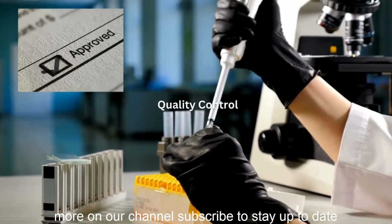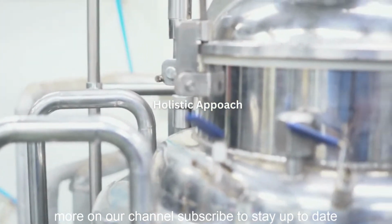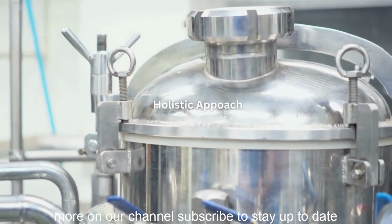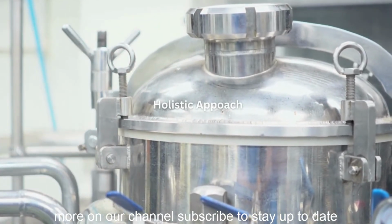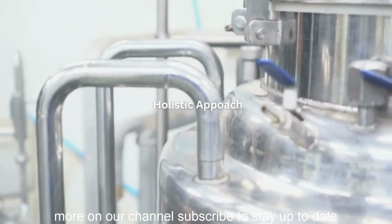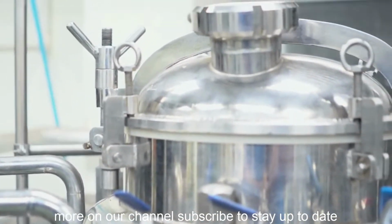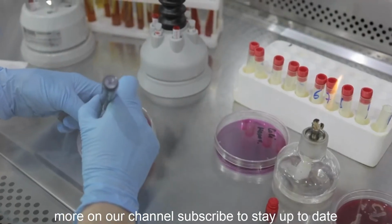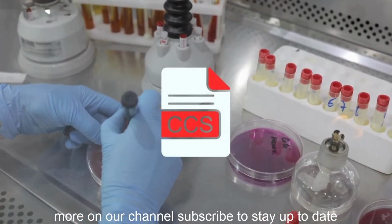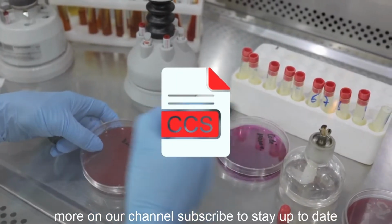The core principle of Annex 1 is to establish and maintain a sterile manufacturing environment. This requires a holistic approach, controlling every aspect of the production process. It starts from the initial design of the facility and extends to the sourcing of raw materials, the execution of manufacturing operations, and the release of the finished product. A key element is the Contamination Control Strategy (CCS), which is a documented approach to identify, assess, and control contamination risks.